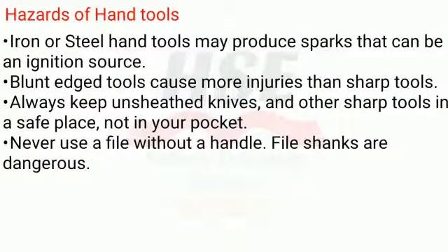Iron or steel hand tools may produce sparks that can be an ignition source. Blunt edge tools cause more injuries than sharp tools. Always keep unsheathed knives and other sharp tools in a safe place, not in your pocket. Never use a file without a handle. File shanks are dangerous.